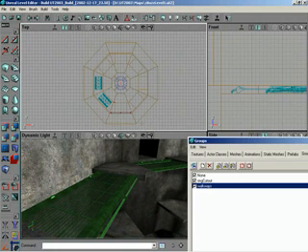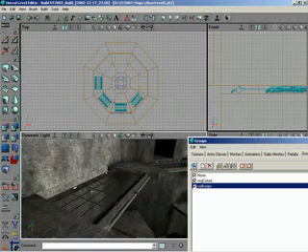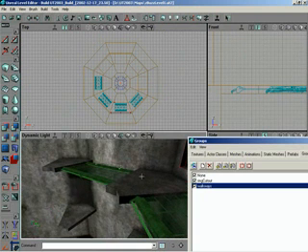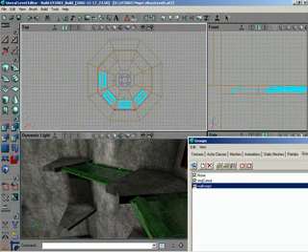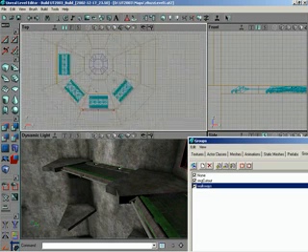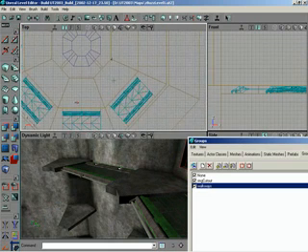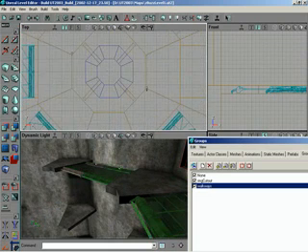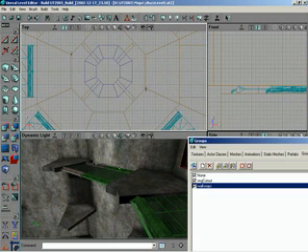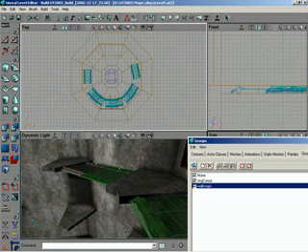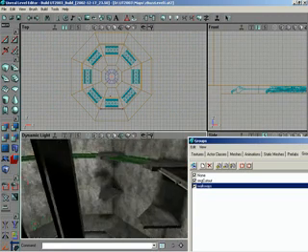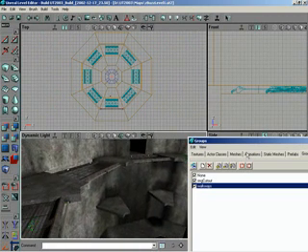Then I can Control right drag to rotate them again. That's very simple. I mean, it's just so cool. So, again, using our ever handy group browser, we can select all of them. Control W, zoom in a little so that I can line them up again, and then place their pivot like that. Okay, I left it center of the world, pivot, snapped here, and rotate those around. And there we have walkways spanning all the way across. That was fast and easy.